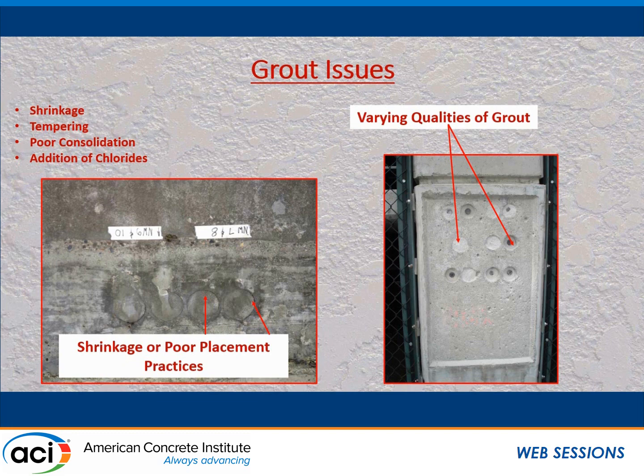But oftentimes, the guys that are putting the grout into the stressing pockets are guys that are filling out the rest of their day. They got 2 hours left on the clock, so go mix up some grout and go pack this stuff in. And they may be retempering the grout, they're not mixing it properly. Sure as heck, whatever grout they're using is the absolute cheapest stuff they can find, because it just doesn't matter to most folks. And so you can get some shrinkage and or just poor consolidation.